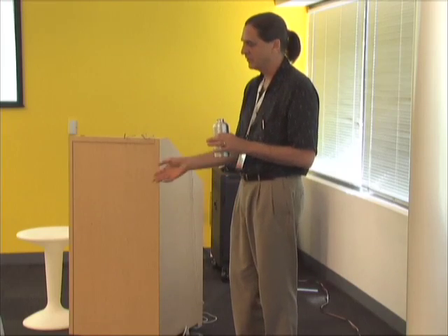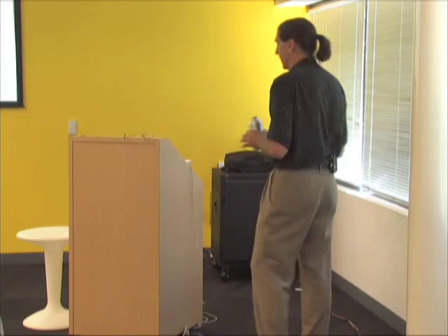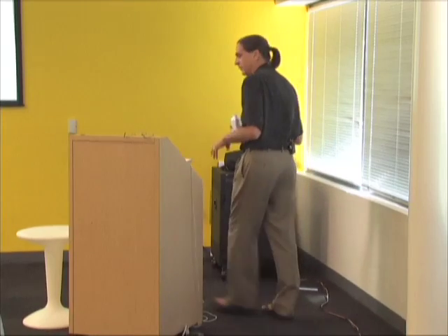And we went back to regenerate the drawings because there was some small change, and the drawings were obliterated. Of course, it was right before I was about to head out to Germany, and I flipped out. But looking at the model, you could see that things were just scattered. So we went back, got an older model, and put all that stuff in. These models are the same way. You need to lock geometry you're not using. You can't lock layers, but you can grab groups and components and lock them.